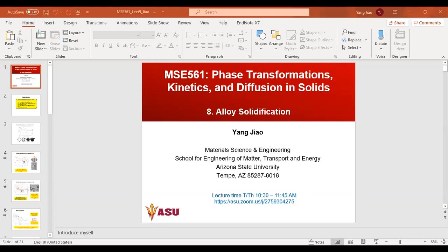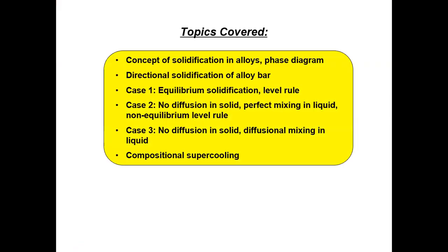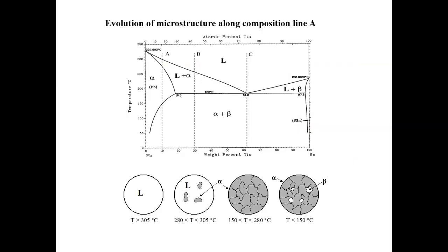As you can probably imagine, the key thing that determines solidification of an alloy is not only the temperature, right? We have to impose the correct temperature to grow, but there's also one important thing involved in the growth or solidification of an alloy, which is the redistribution of the solutes. If you still remember, if you look at any phase diagram, during the solidification process the equilibrium compositions of the liquid and solid phases are constantly changing.